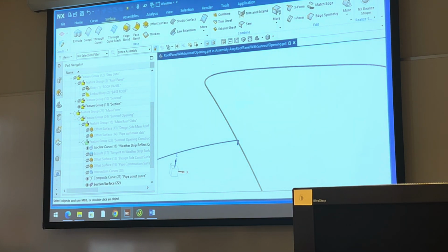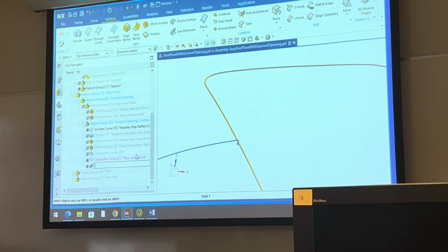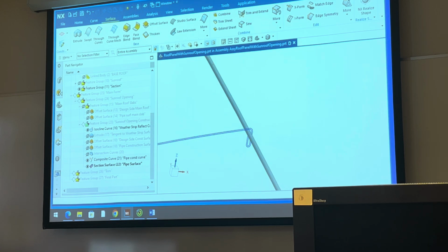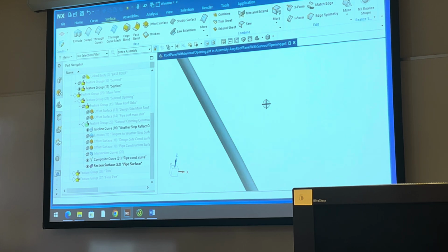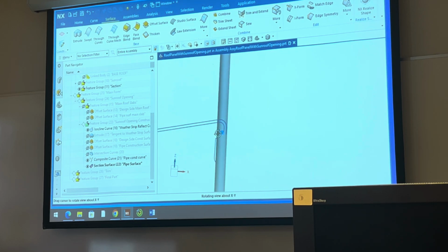And that's a circular shape, so I don't know. Yep, we're gonna call that pipe surface. So after all that, we didn't use the tube command, we used the section surface command. We could have used the tube, and it's the same concept, right? Now, I'm gonna make a reflect curve on the inside of that, because, and here's where it kinda gets messed